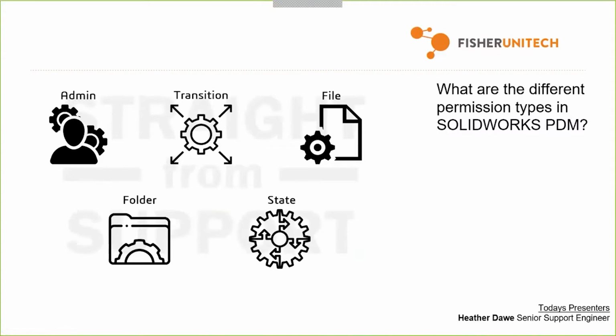Most of these have components that may be unique to PDM Pro, but there are permissions for admin, folder, transition, state, and file in both PDM Standard and PDM Pro. All of these permissions exist in both, and I'll be sure to specify when a specific permission is only in PDM Professional.